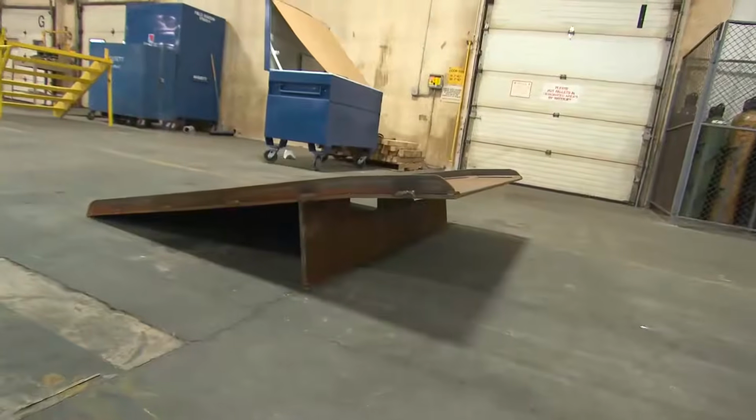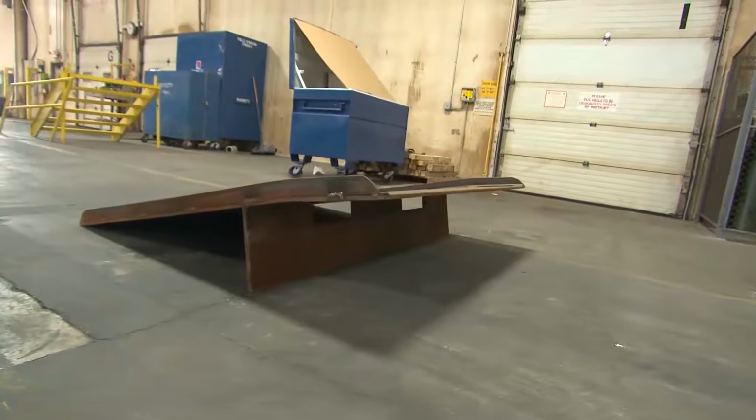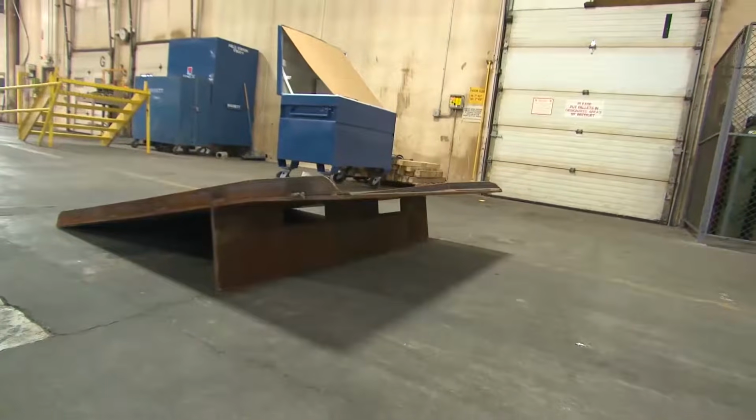There's more. Fall protection may need to be installed on dock boards where there is the potential for falls to a lower level. If you're using portable dock boards, they should be equipped with handholds or other means to permit safe handling. They must be secured by anchoring in place or using equipment or devices that prevent the dock board from moving or shifting out of place. Some dock boards have adjustable locking pins that help prevent movement or safety stops on the underside of the dock board that fit between the dock and the vehicle.